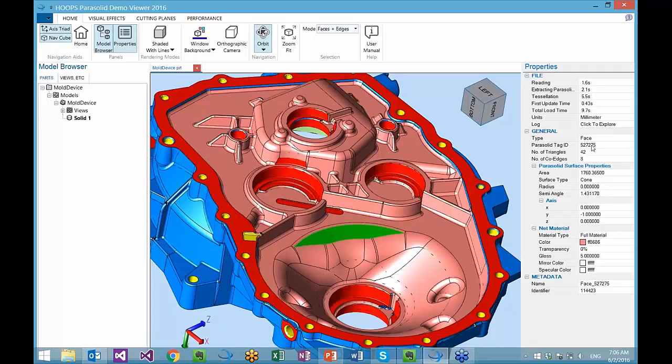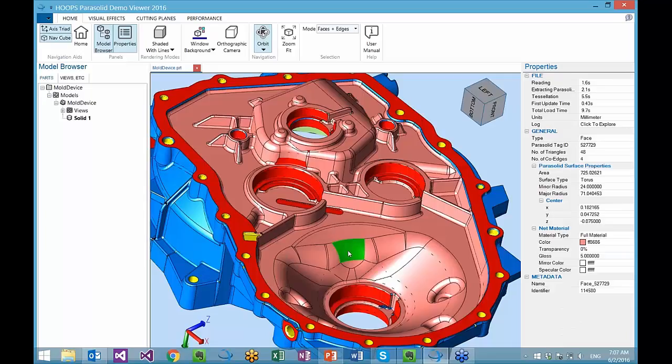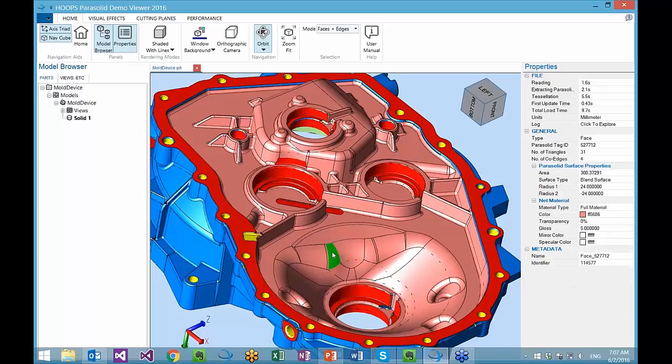Additionally, we have the ability to give you edge data and project points to your surfaces and your different edges. But what about some more complicated surfaces? Many times when you load a file, it has to go through numerous steps and different other types of technologies. If you were to load a more complicated surface like this, a blend surface here between the cone, a torus, and then we have a more complicated blend surface, many times you would have to load that from the file and then convert it into a form that your internal system requires, so your internal data translation system.